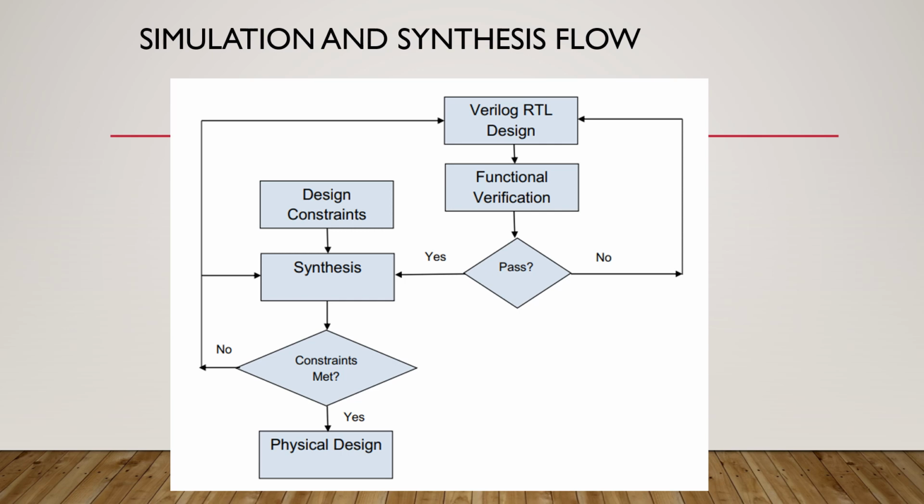Actually, the designers start from the Verilog RTL design. I already told you RTL means Register Transfer Level. Any complex circuit can be described by means of RTL. It is a high level abstraction, that is, we are dealing only with the registers, not with the exact structure. So any complex circuit we can easily design with the RTL design.